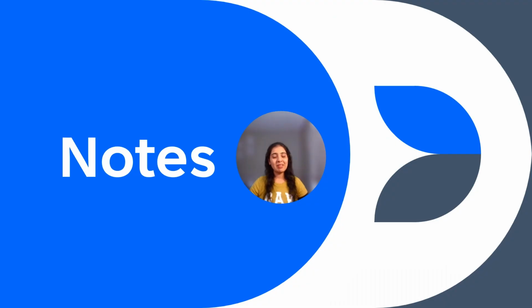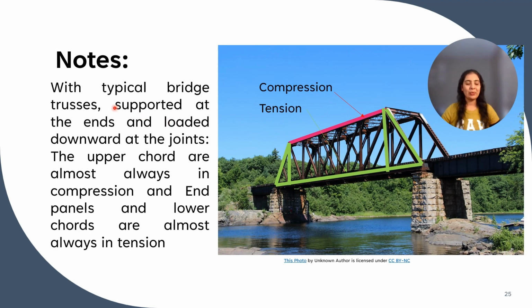Now we will see some important points about trusses. Note: with typical bridge trusses supported at the ends and loaded downward at the joints, the upper chords are almost always in compression, and the end panels and lower chords are almost always in tension.